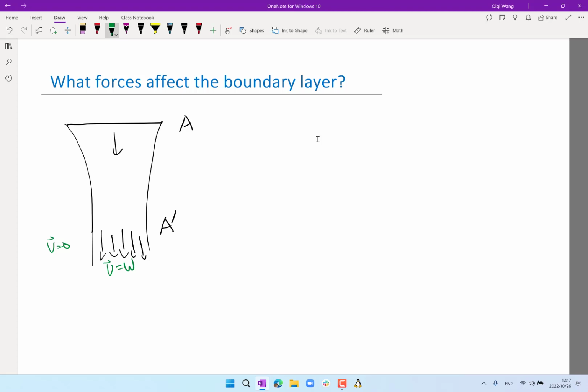As a result, the stagnation pressure jumps. All right? So the stagnation pressure here is higher than the stagnation pressure here, which if you follow the streamlines is the same as stagnation pressure very far away from the rotor, which is going to be the same as the stagnation pressure over here, right? So stagnation pressure here is higher. So that's one way to think about it.